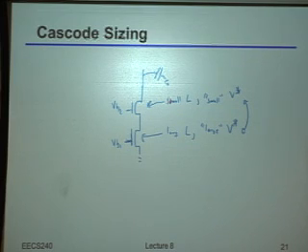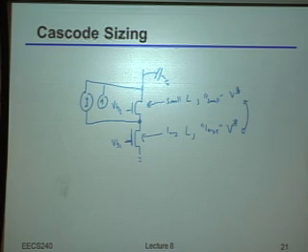Yes? Just to check, so if you have a current source, like the noise current coming from the upper transistor, from the cascode device? Okay. Why doesn't that see the impedance at the top? Like, why does that see the impedance at the middle node? Oh, okay. So the question was, if I add in the noise current source, and I'm just going to draw it on the side here so that I don't clobber other stuff, why is it that it's only seeing the 1 over GM down at this bottom node as opposed to the impedance looking down over there?